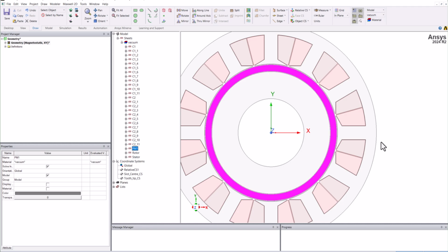Now this time we have to create a cutting section to create a single magnet out of this magnet ring. How do we do that? We know that for any number of poles, 360° divided by the number of poles would be the maximum pole angle, or 180° electrical that a pole will be able to occupy. So here again, using the same right angle triangle rule, I am going to find what will be the y point over here.